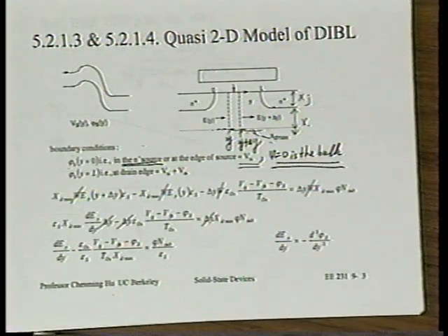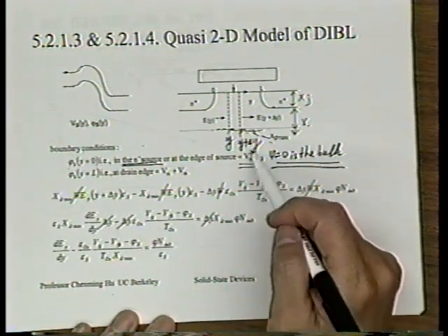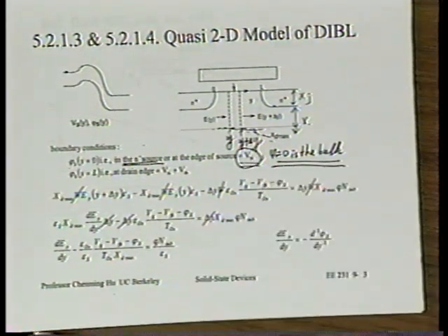Is that right? Yes? So if the neutral region of the P is 0, what is the potential of the neutral region of the N plus source? It's the source body built-in potential, right? Is that right? And there are no ifs and buts about that, because that's just determined by the doping concentration of the body and N plus source.